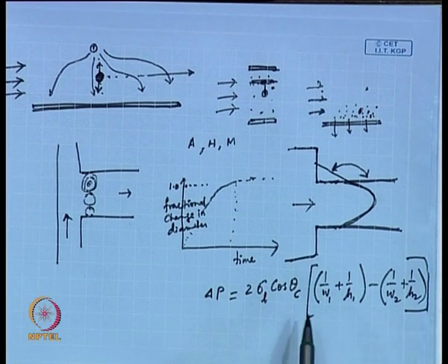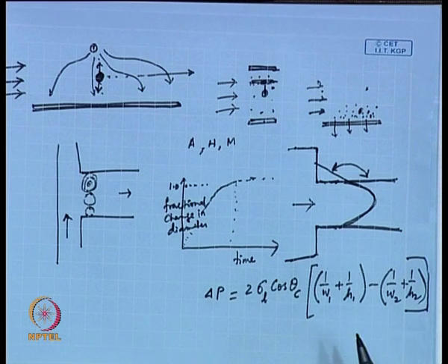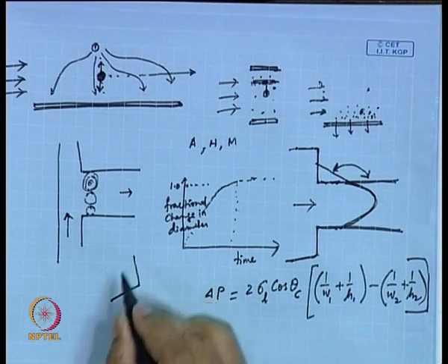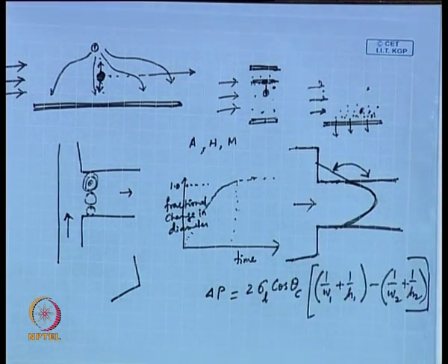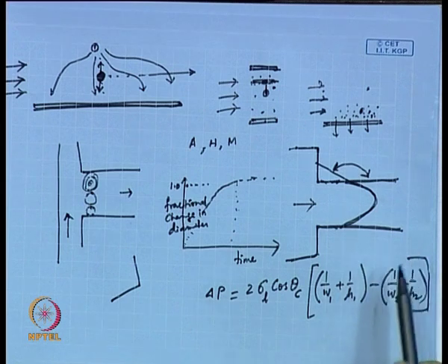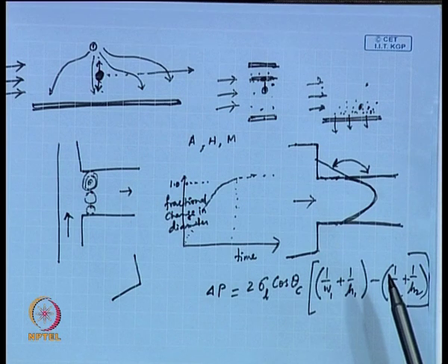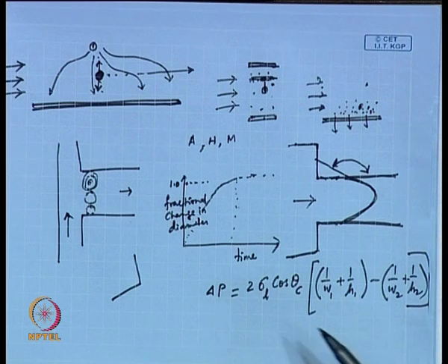So, this is the pressure drop that you have. This is the pressure difference between the liquid menisci. Of course, you will ask what W1 and H1 are. This channel is considered to have a width W and height H. It is not exactly a circular channel; one channel has width W1 and height H1, and the other channel has W2 and H2. These are the dimensions of the channel, theta c is the contact angle, and sigma L is the interfacial tension.